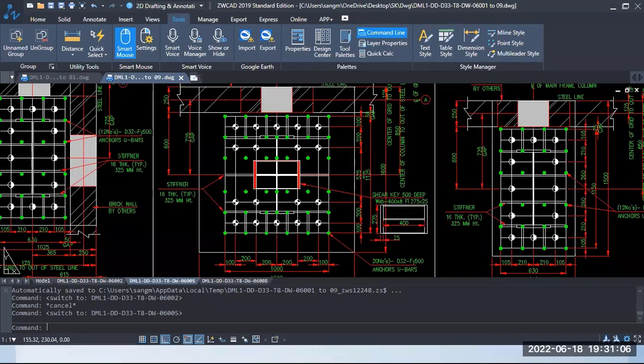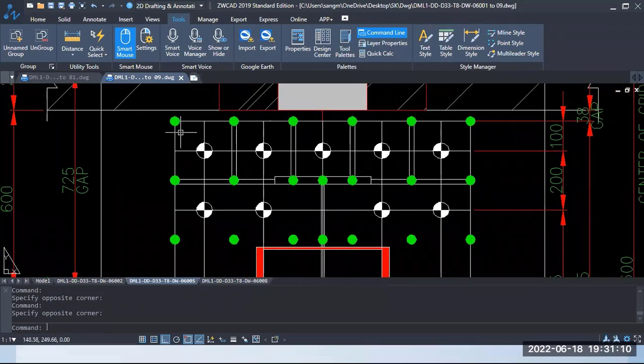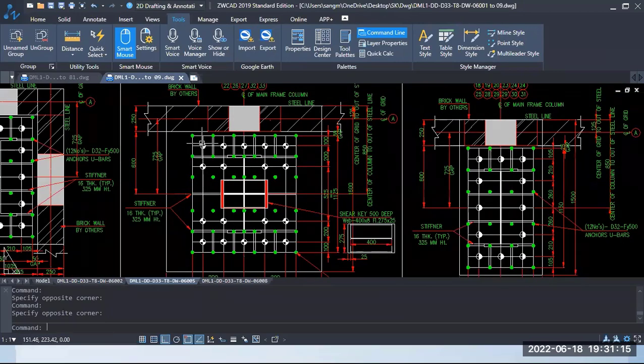And these are the anchor positions, and this is the I section. Okay, and the green color is what you are seeing. These are the additional reinforcement we have provided to safeguard the pedestal. As in the American codes, we have to check the concrete capacity as well.